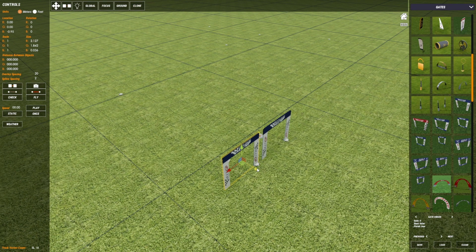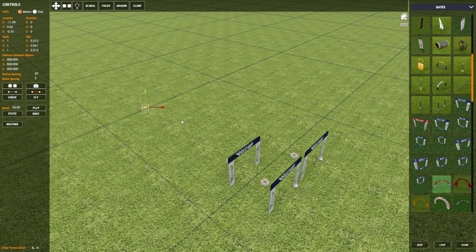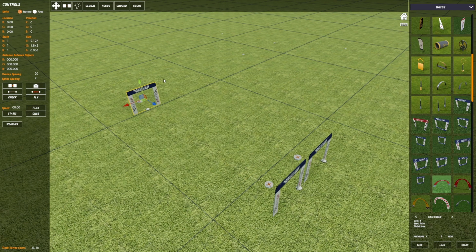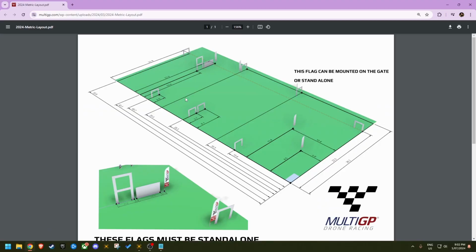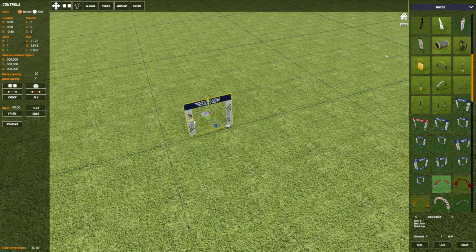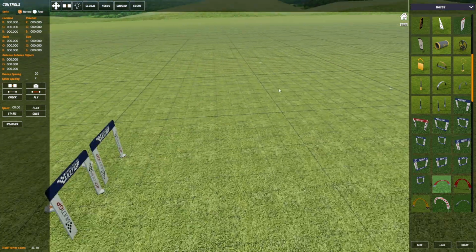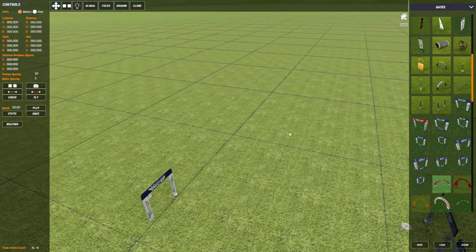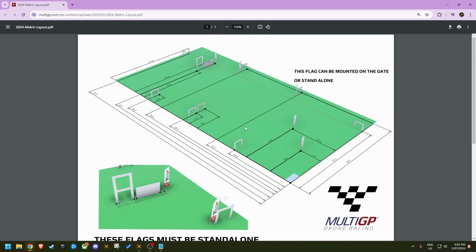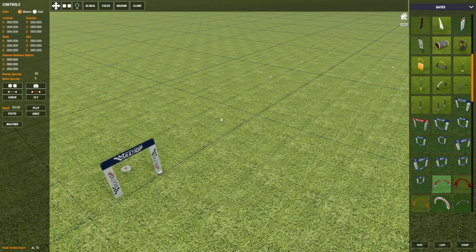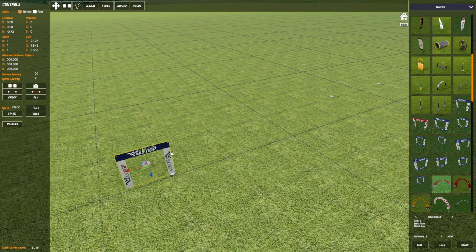And I can clone this gate, move it up, set the cone as the 0 point, move the gate, and then this one also, right side of the gate is on top of the cone. Just like that. Now we've done 3 gates accurately. I'll cover the double gate and then that's where I'll end this guide.